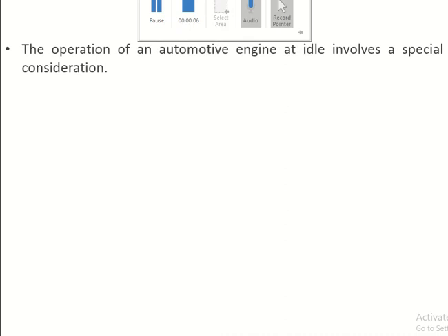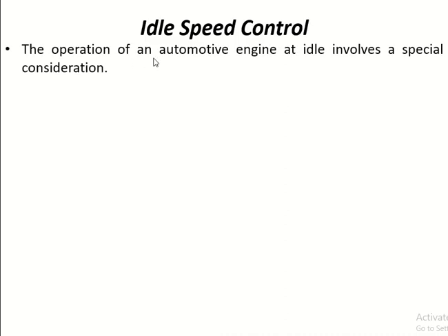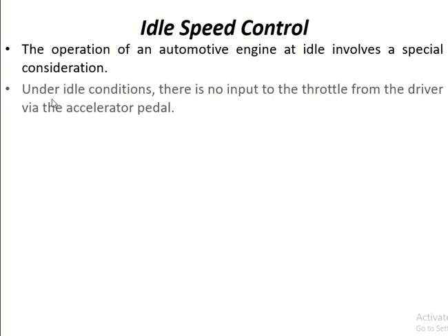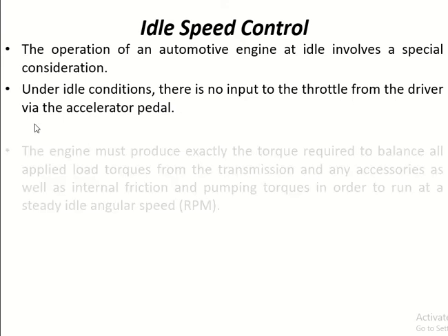Today's lecture, we will discuss idle speed control. The operation of an automotive engine at idle involves a special consideration. Under idle condition, there is no input to the throttle from the driver via the accelerator pedal.